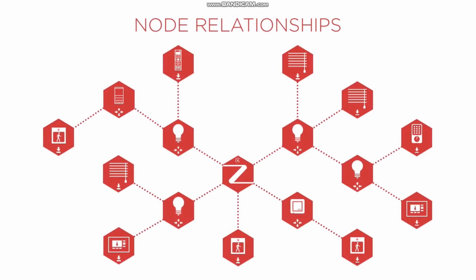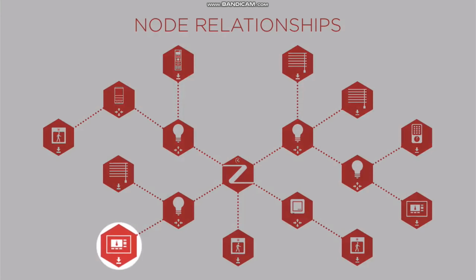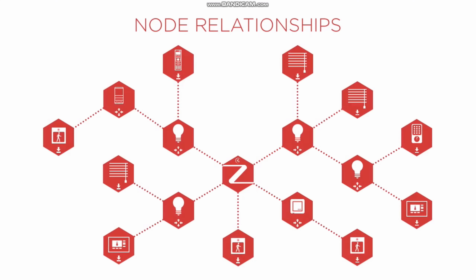Here's an example of how a Control4 ZigBee Pro mesh network operates. A packet intended for the thermostat end node in this network starts at the mesh controller, is sent to a routing lighting device, and then to the thermostat. Control4 ZigBee Pro contains self-healing features that make it a preferred choice for automation devices. Watch how this works. If a router node falls offline for some reason, ZigBee packets can be routed to the next nearest neighbor so that they can still reach their destination.